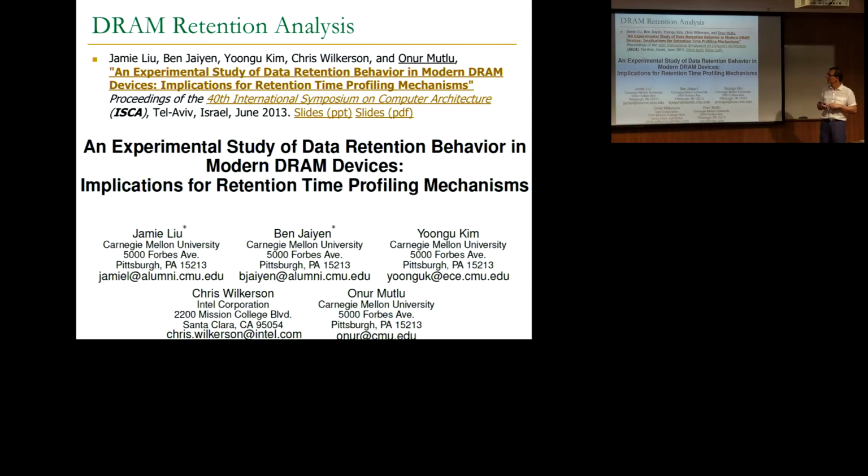One of the findings is that most cells are strong. You don't need to refresh everything every 64 milliseconds. A lot of cells can retain data for hundreds of milliseconds.